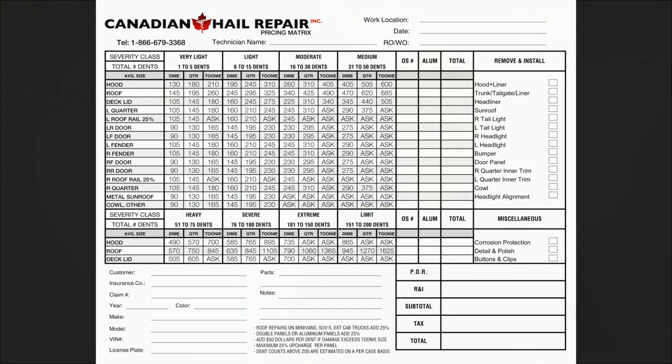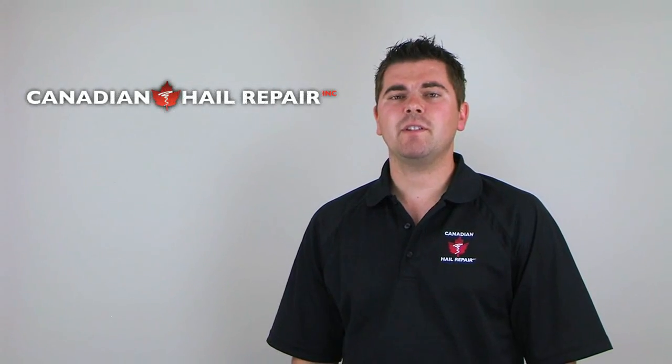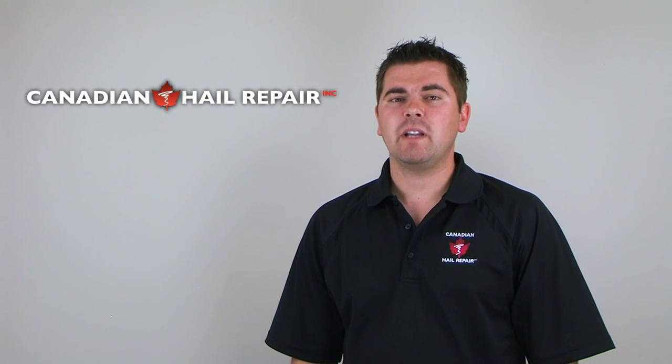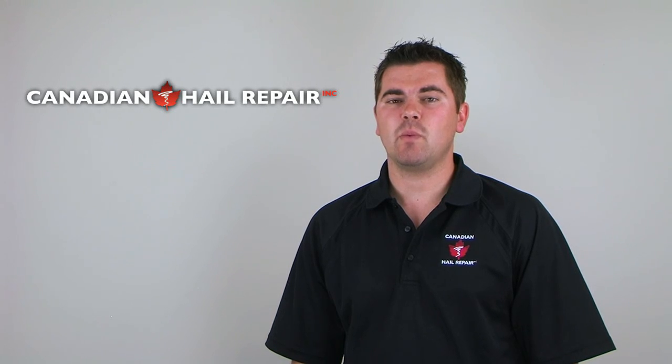Some of you may be wondering how to determine which size of dent to put on the matrix, because there may be different sized dents on this panel. Take for instance a hood with 31 quarter-sized dents and 20 dime-sized dents. We will write this up on the matrix as a heavy hit quarter-sized dent. This shows that we use the dents representing the majority size when estimating.